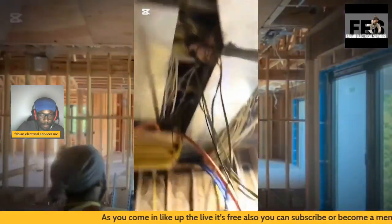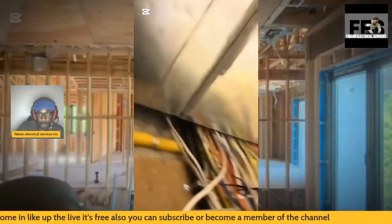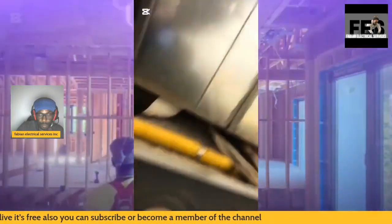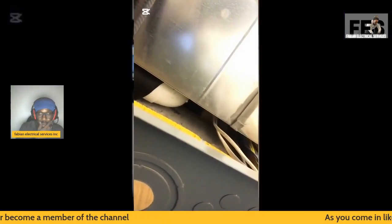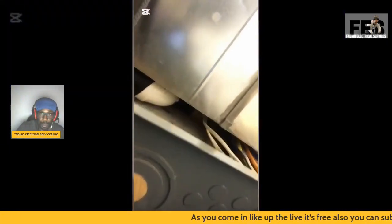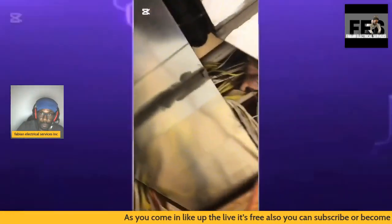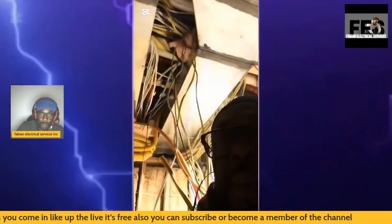As you can see, this is a pretty big job that I'm carrying on here. Also, you can see the wires touching the duct. That has to be within code compliance, so I'm going to have to place some insulation between my wires and the duct to stay within my code rules.